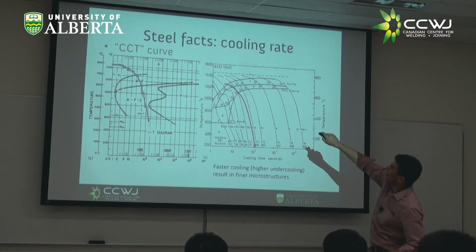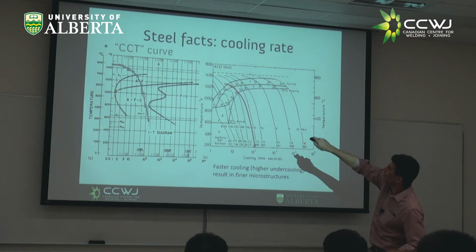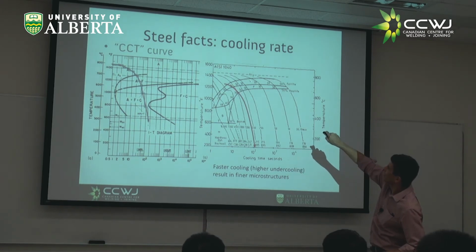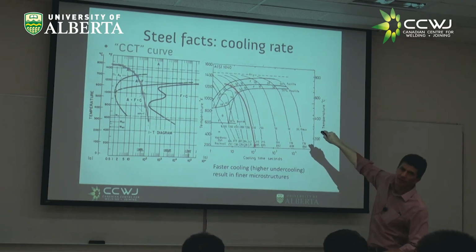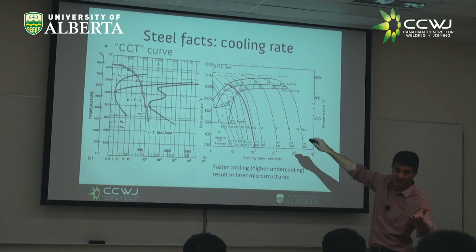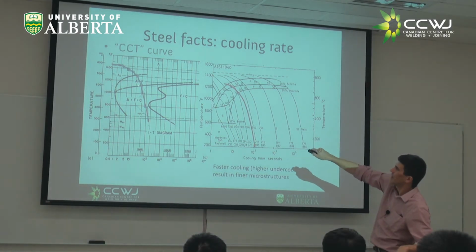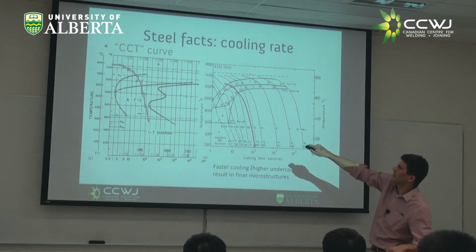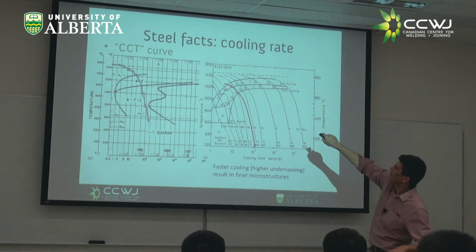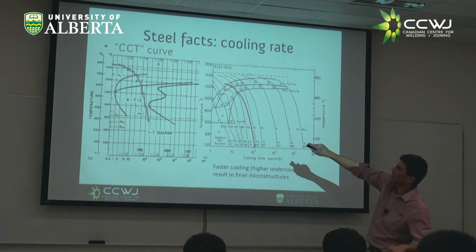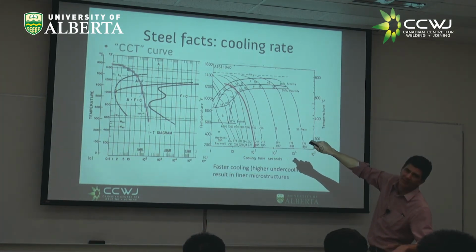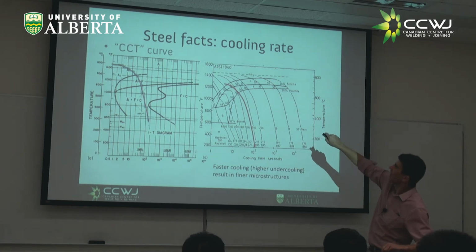So at the beginning you have austenite, just as before, and then you would have this F. What do you think this F stands for? Ferrite? Primary ferrite. Proeutectoid, yes, that's another proper term. This is what it says here. Here it says A plus F. Here it says only F. What is A plus F here? Austenite plus ferrite. Why do you think I have austenite here or not?